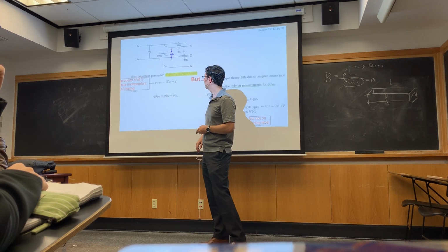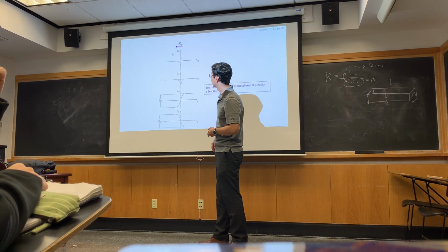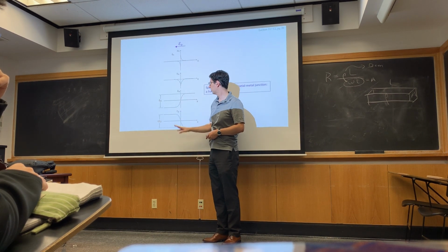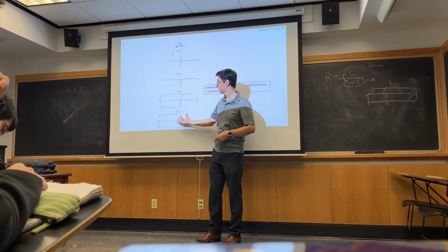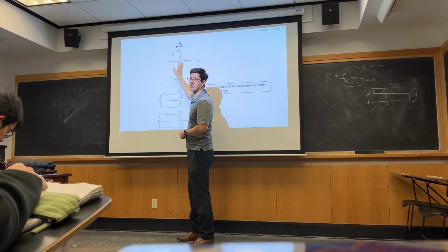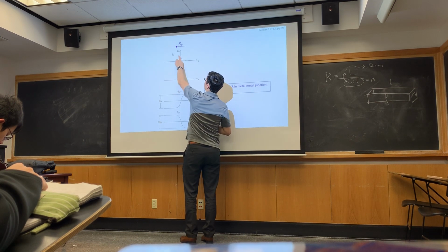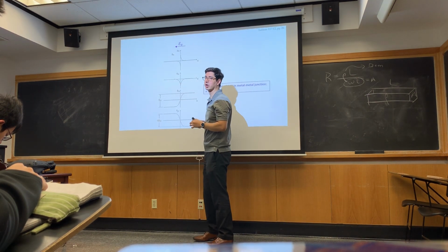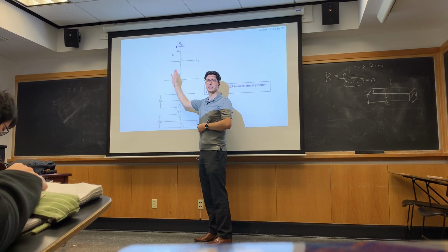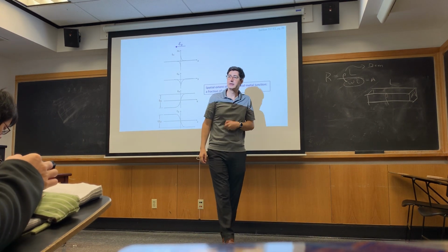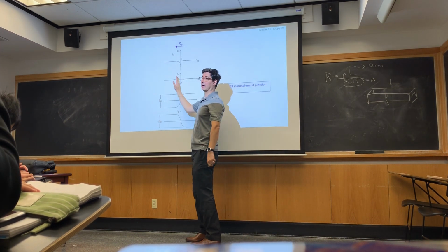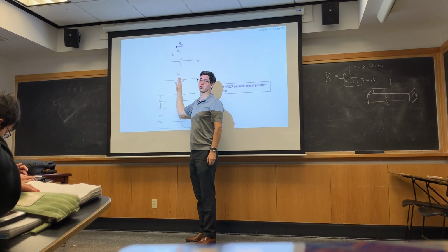Well, how did we get that? Well, we had these types of band diagrams, or we had these rho, electric field, potential, energy band diagrams, right? And we could see that it was really lopsided. If this was a spike here, and this was a broad thing over here, you don't get much potential drop on the side with the spike. And indeed, you don't. For the metal, it basically is a spike right at the junction.